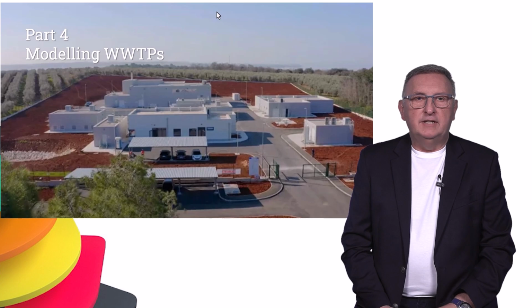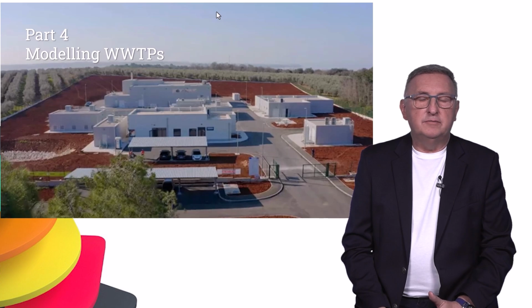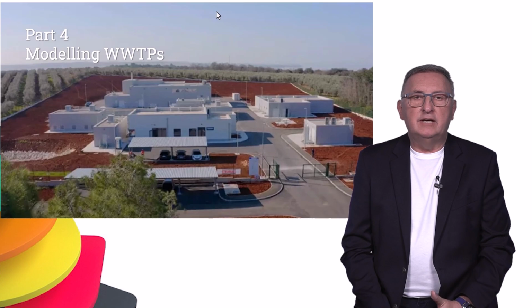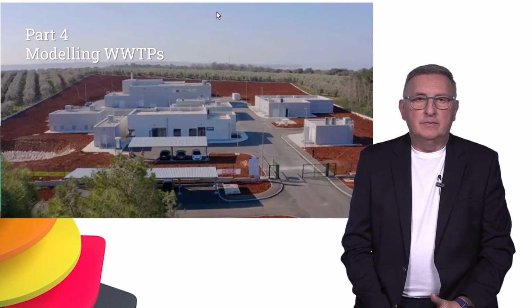At this stage of the study, we have successfully completed the modeling of the 4 sewerage catchments. We completed quite extensive analysis of sewage quality and of seawater quality. And now we have enough information to enter into modeling of the 4 wastewater treatment plants. What is common for these 4 wastewater treatment plants? That they applied identical technology. Only the capacities are different. And of course, influent quality is different from treatment plant to treatment plant. But the treatment process is the same.